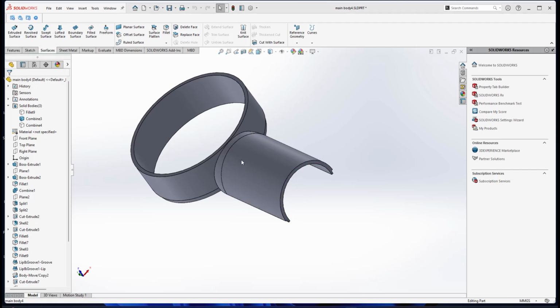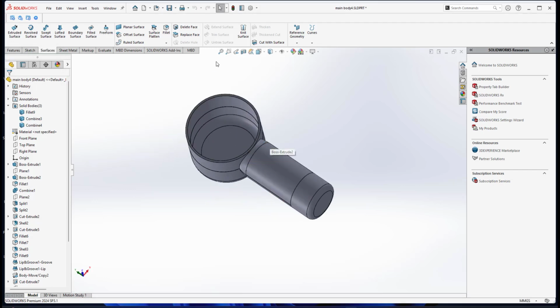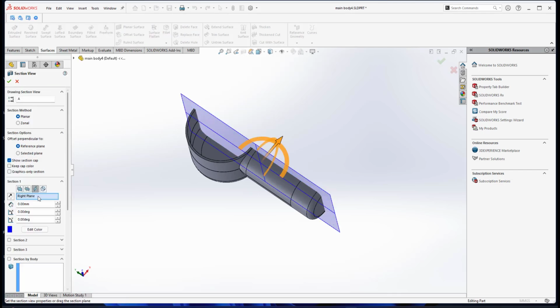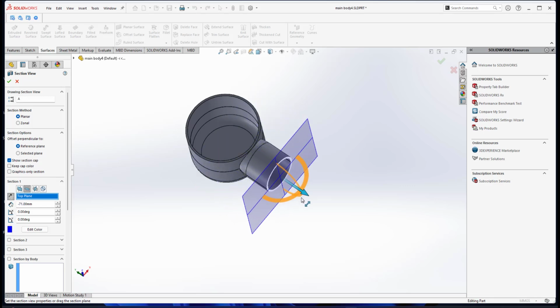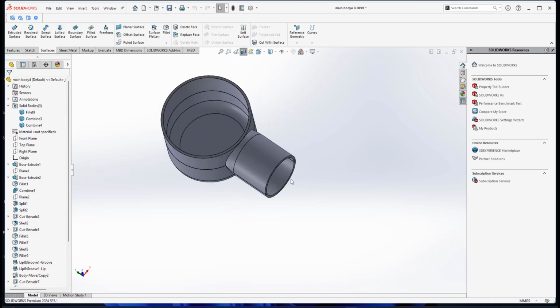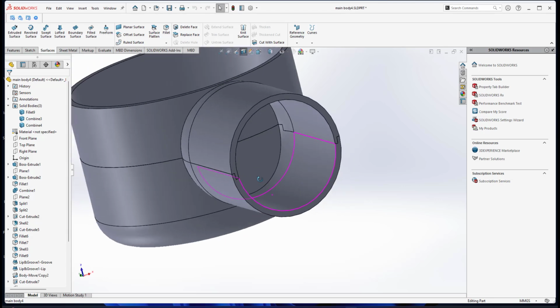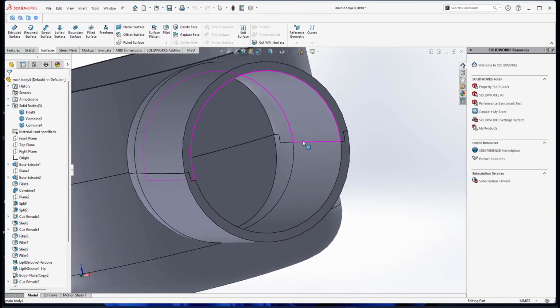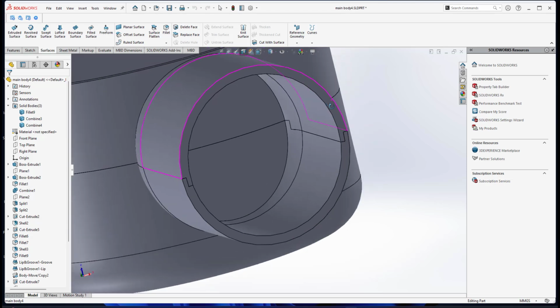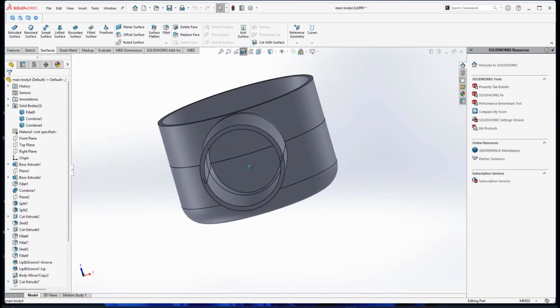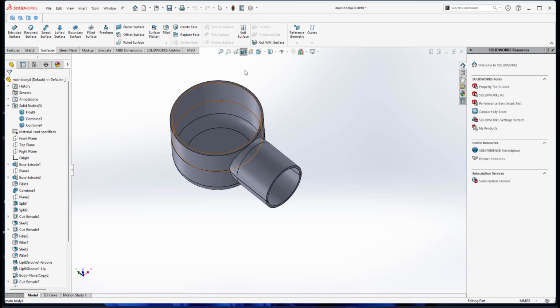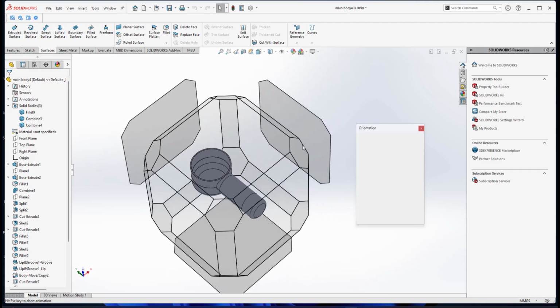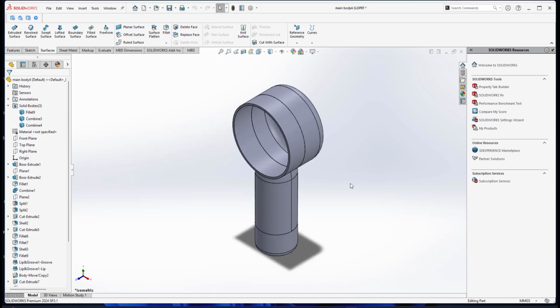So that's how I do it. If I show you the section view, this section view like this. If you look at the result, we have nicely the lip for the front casing, and we have the groove for the rear casing, right? So that's how I do lip and groove manually for this case.